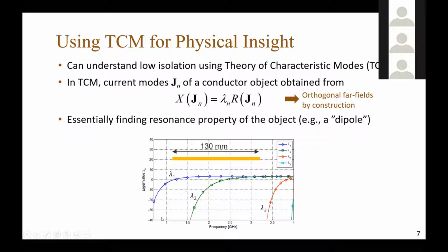If we confine the eigenvalues to plus minus 40, you can see that at this frequency, you only have one eigenvalue of this small value. We're solving this across frequencies, so if we trace how this eigenvalue is going, then when it crosses zero, that's where the resonance is.